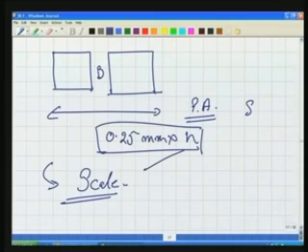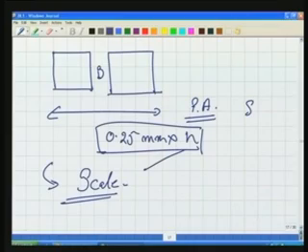Having seen all these things, we have seen some principles of surveying. For example, in any mapping exercise, we must do the reconnaissance, number one. Number two, we should establish a control network, because we want to work always from whole to part. And we fix the control network in our area first. I gave you the way we can do it by triangulation. We will see later on that we can do it by many methods.